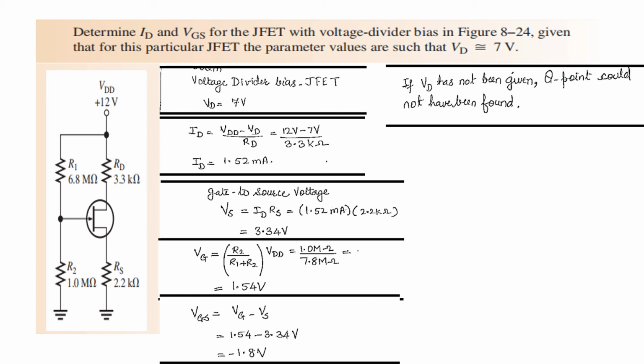The idea behind determining the stability of the amplifier, defining it as linear or non-linear, is that we should get an accurate, amplified response at the output, and not a clipped signal. Therefore, if a circuit is to be operated as an amplifier, it has to be stable, working in the linear region.